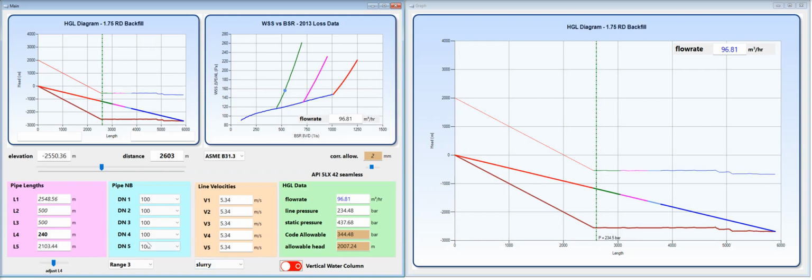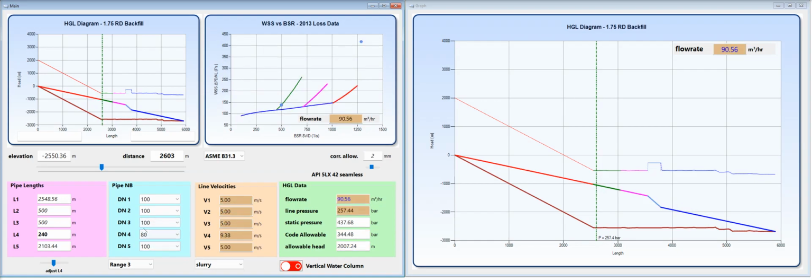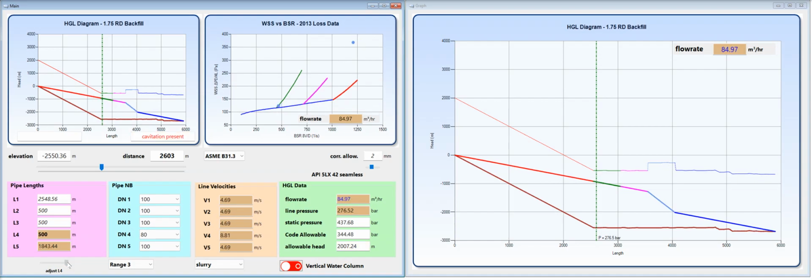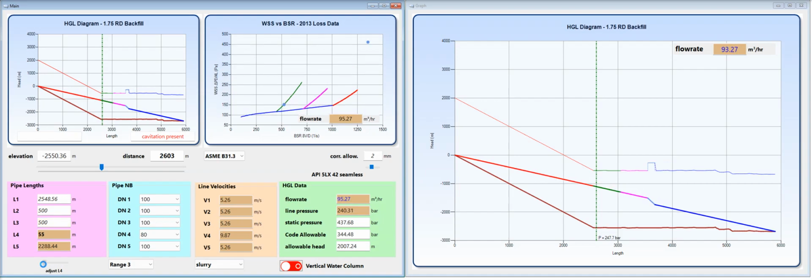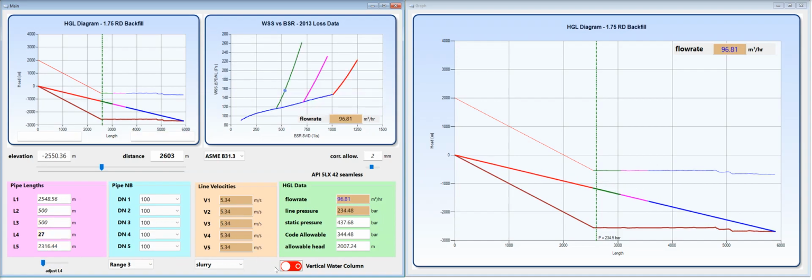I can show you the effect of a choke. A choke is a reduced section of pipe diameter. If I increase the choke, the flow rate drops. If I decrease it, the flow rate increases. Let's take the choke out.